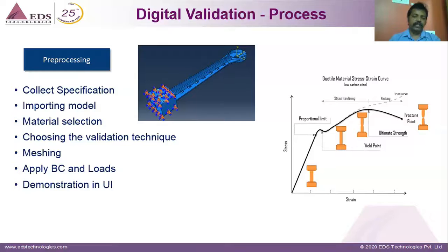The next stage is that you fix the arm at one of the ends, you apply the boundary condition, you do the meshing part, and then you push it to the solver, where the solver is basically a ton of algorithms, consisting mathematically of differential equations. It tries to solve for each and every node, and then tries to find the equilibrium for each and every equation. If this equilibrium is satisfied, it goes step by step, which is known as iterations, and then you end up with the final result.